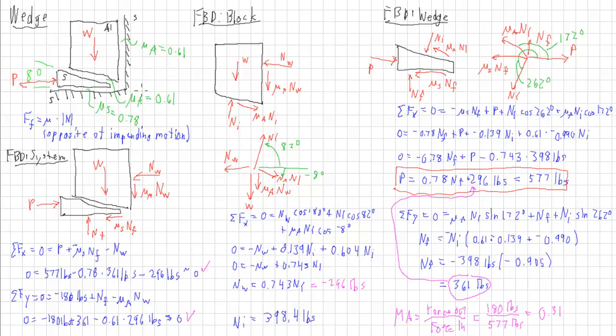Well, once we had this set up to get out some form of mechanical advantage or some design that we were hoping to achieve, to analyze it, we looked at the system and looked at all the different forces on the system, realized that we didn't have enough to solve it from that. We chose the free body diagram of the block because we had two equations and two unknowns. We solved for them.